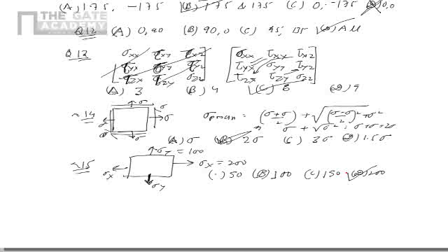And everybody should do a lot of problems on this, especially on the transformation rules. Please try to remember the basic formulae directly without deriving them in the exam. There is no time to do that. Please remember the formulae for maximum principal stress and maximum shear stress, and the angles of maximum principal planes and maximum shear planes, as well as the transformation rule, which is like sigma in some direction will be equal to sigma x cos square theta plus sigma y sin square theta plus 2 tau xy sin theta cos theta.